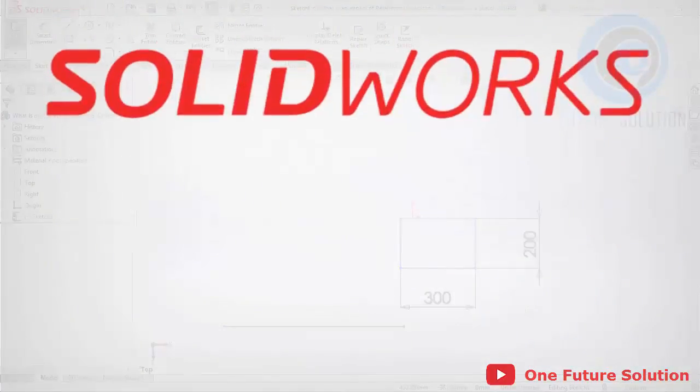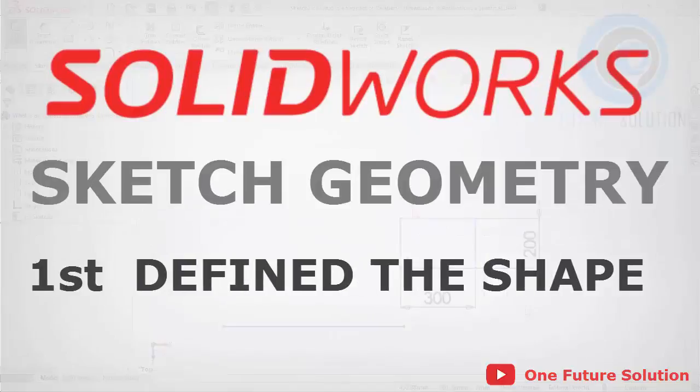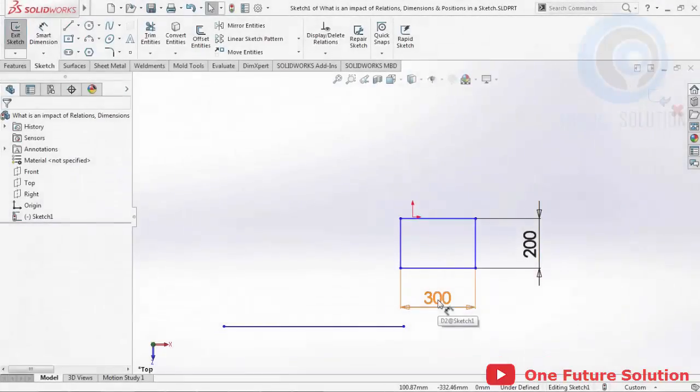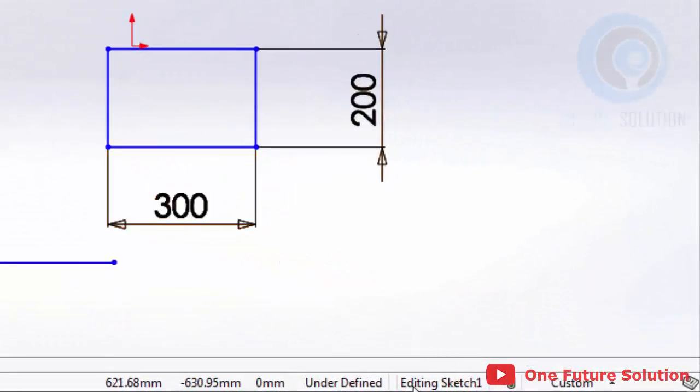In SolidWorks, if we want to create a sketch geometry, the first step that we should do is define the shape. After that we can add the dimension of that shape. So we should focus first on the shape of the sketch geometry. This will make our imagination of the sketch shape better than creating the line while inputting the dimension at the same time. Okay, now, look at the status bar. The status bar shows us this sketch is still underdefined.